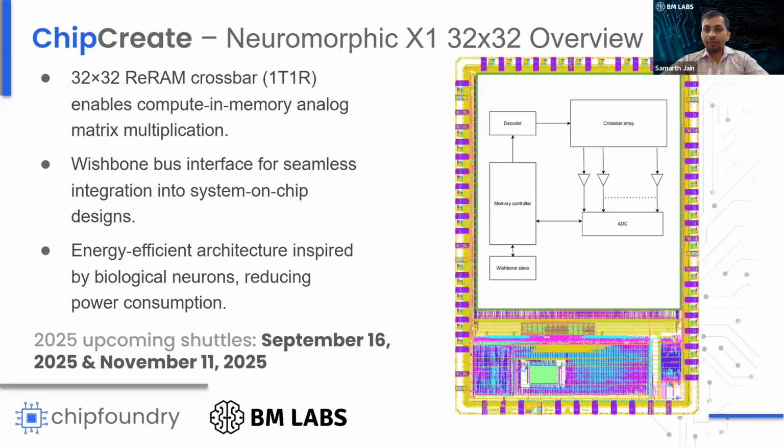Yeah, so we have tested endurance at 125 degrees C. We heat the chips and we check. We program the ReRAM for 24 hours at accelerated temperature. We have multiple of these SoCs, and then we read back each cell to make sure that the state remains the same. We do offer this data for interested customers. We provide endurance at elevated temperature and at room temperature.